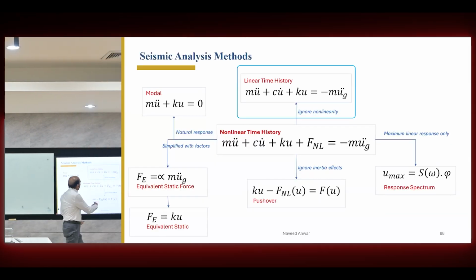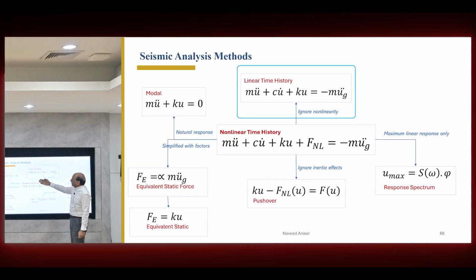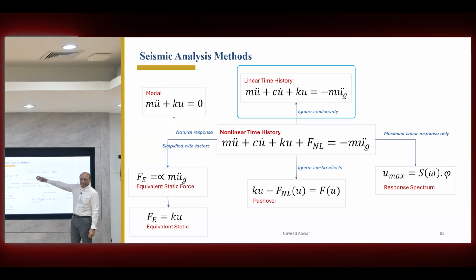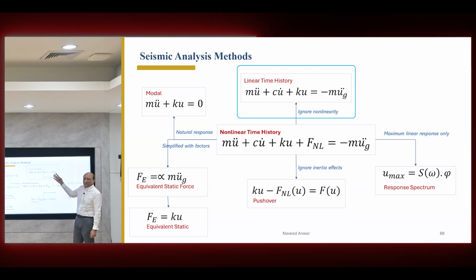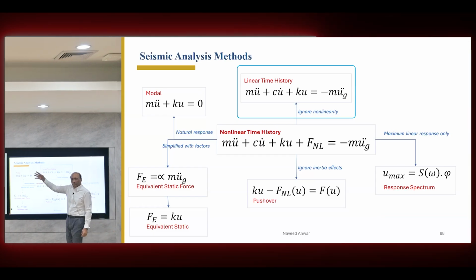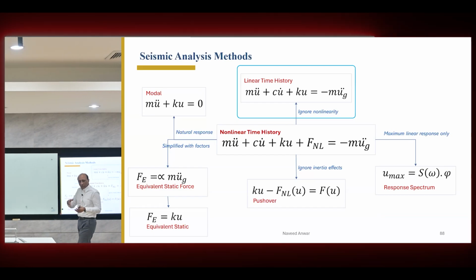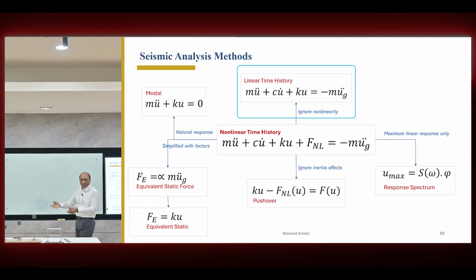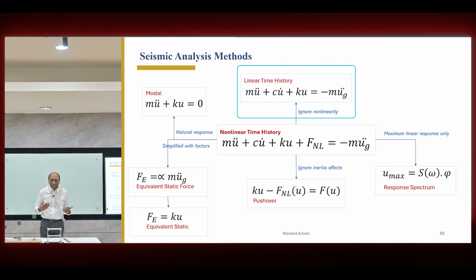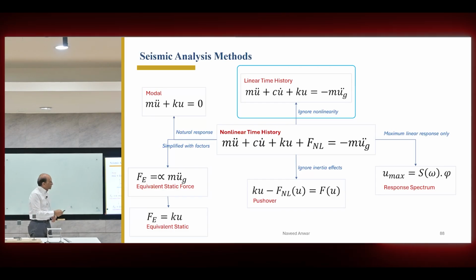So now we say, okay, we have this equation already. We have the model, so everything is there that we need. The damping we need is already there. The stiffness is there, mass is there. And the ground motions that we use to generate the response spectrum, if we bring those ground motions, or we convert the response spectrum into ground motions, either way, you can then input the ground motion directly and then run the analysis. So that's the next step that we just skip.